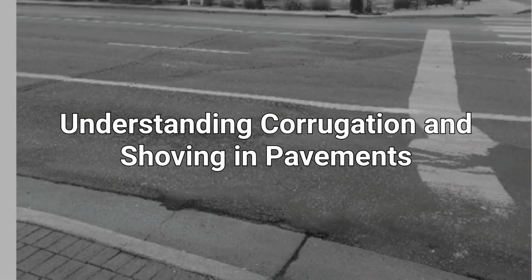Understanding corrugation and shoving in pavements. Corrugation and shoving is a ripple, corrugation, or an abrupt wave, shoving, on the pavement surface at points where traffic starts and stops, corrugation, or areas where asphalt abuts a rigid object, shoving, as shown in Fig. This is a form of plastic movement of asphalt materials perpendicular to the traffic direction and does not accompany cracking. Corrugation and shoving is usually caused by traffic action, starting and stopping, on less stable and less shear-resistant materials, which is because of the following reasons.